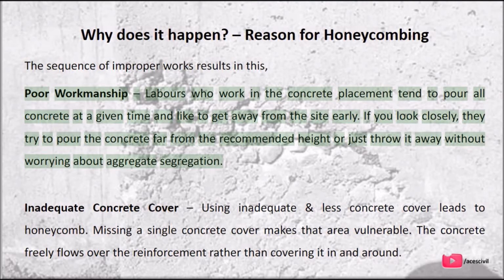Poor workmanship. Laborers who work in concrete placement tend to pour all the concrete at a given time and like to get away from the site early. If you look closely, they try to pour the concrete from far above the recommended height or just throw it, without worrying about aggregate segregation.